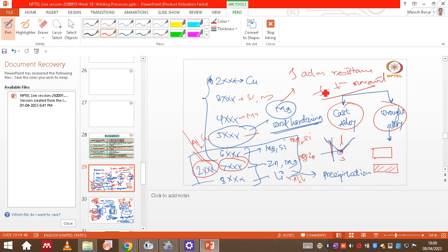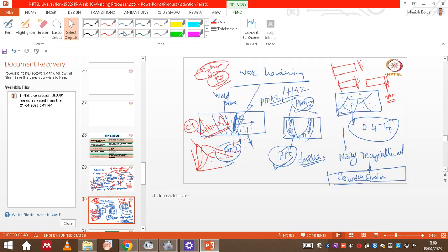Okay, so in other words, in a cold work hardened material, the higher the dislocation density, the higher the strength of the material and the lower the ductility, right? So why am I telling this? Because in fusion welding processes we are melting the interfaces, right? And because of that, heat will be transferred to the surrounding region, and that heat leads to a